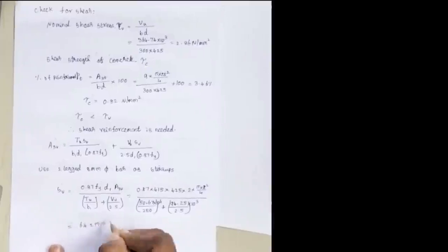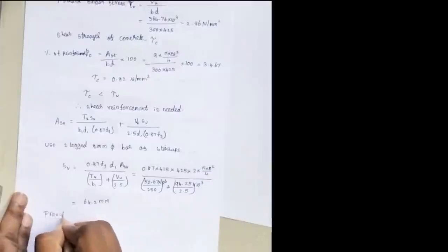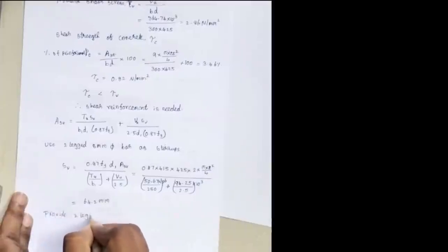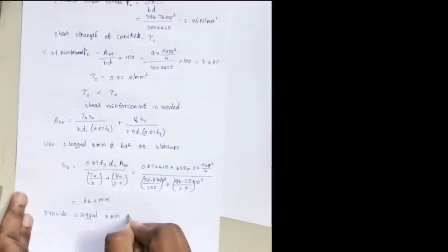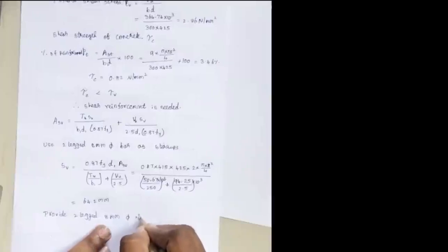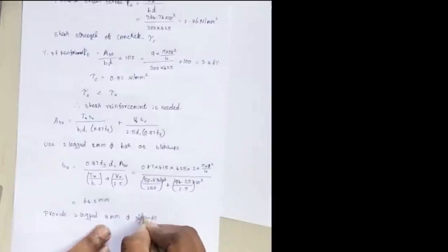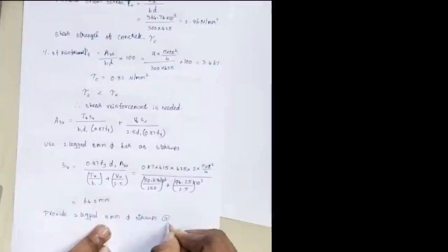So I need to provide two-legged 8 mm dia stirrups at 60 mm center to center spacing.